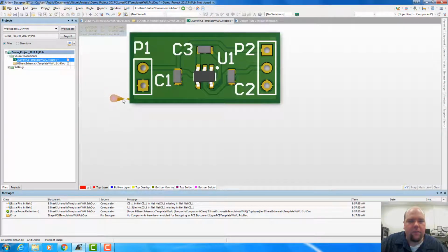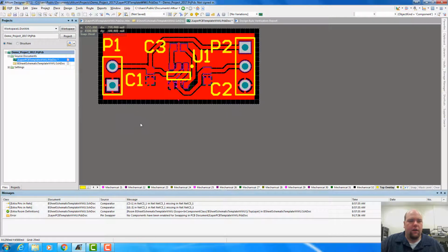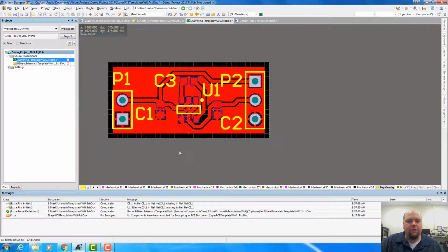Okay, that's a little bit better. Now, different fabs too. Some fabs don't like you ever letting the board outline. Sometimes they don't let you put a plane right up against the board edge. The fab that I use is okay with it. But just note, if you do have a plane that goes right up against the edge of the board, there's probably going to be an exposed little copper edge there when it gets cut. There'll be a little bit of copper shown there.